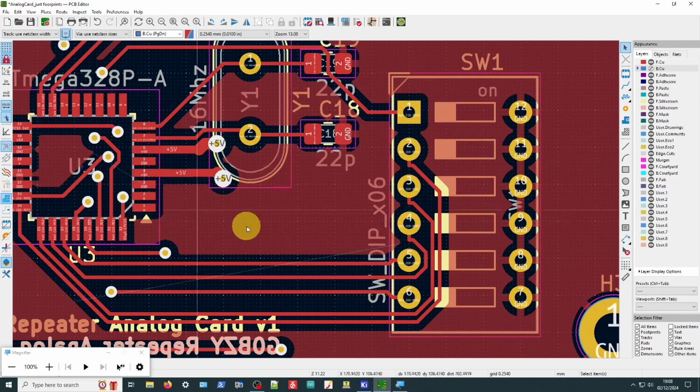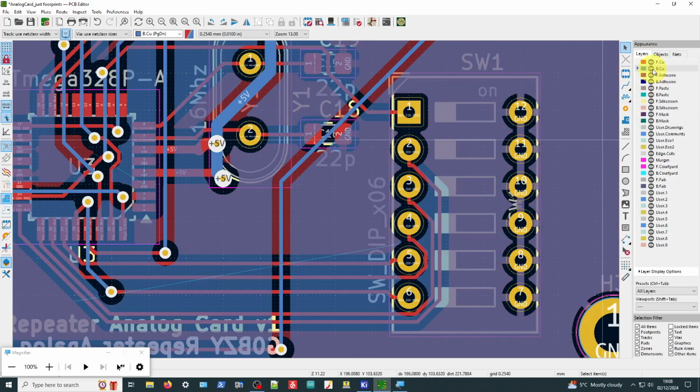Now, the easiest way around that is, all I do is I just put via pins through the board, to connect it to the other side, and then it makes it ground. So if we do that now, I'll turn on the back layer. Let's get a wire pin and stick a couple of wires in here. I'm just clicking them in here.